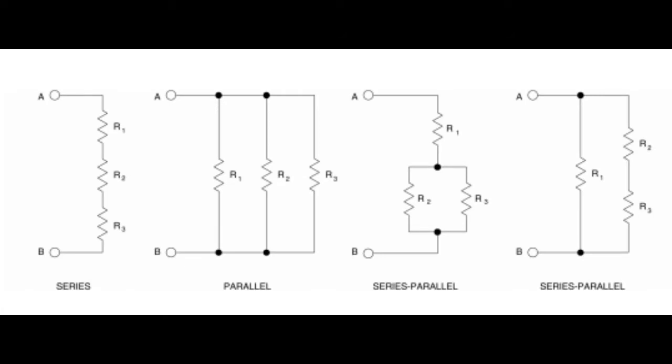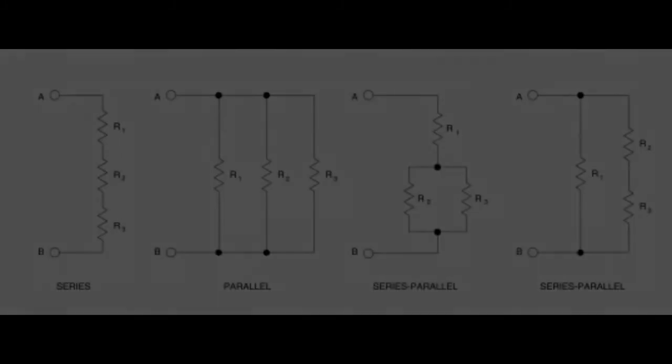Based on the discussion, we may now say that every circuit is a combination of series and parallel resistances. Therefore, in order to get the total value of any series-parallel resistance circuit, we must apply the laws for adding series resistances and parallel resistances. After getting the total resistance, we may replace the circuit with its equivalent resistance.